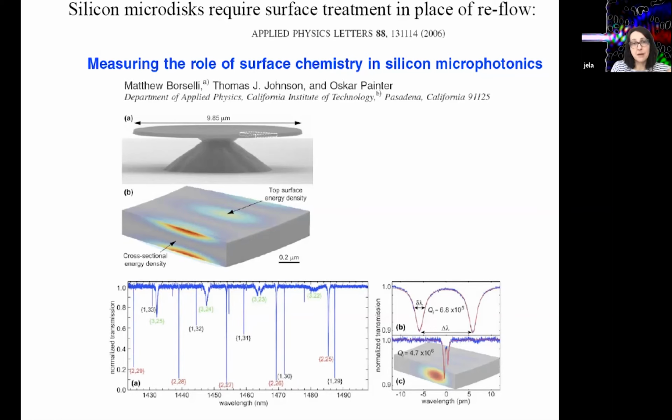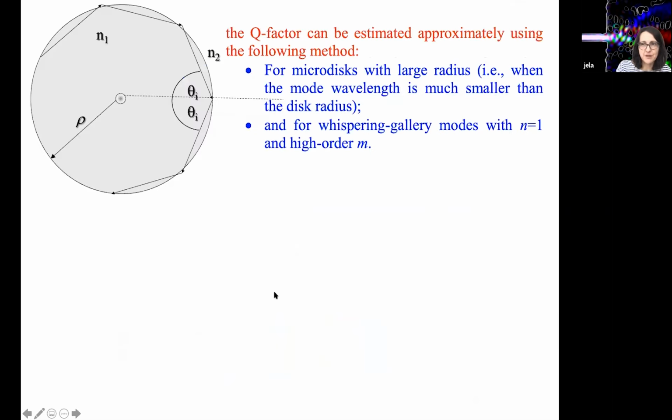The pedestal is not necessarily completely symmetric. That depends on how you are etching the substrate, and whether it is an isotropic or non-isotropic etch. So maybe it has to do with how the cosine and sine modes are interacting with it. This is my guess. I don't know for sure because I was not involved with this work.